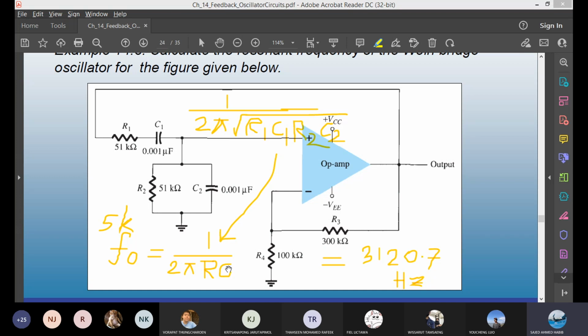If you remember the voltage control oscillator from linear digital circuits, VCO, for a good VCO there are some design limitations. The resistor has to be within a certain value, and then applied voltage, VC, and frequency all have to be within a certain value. Here you have a bit more liberty. We don't have such strict criteria, so you can pick any value of R which is sensible. For example, what you can find in the lab: 100K, 50K, 70K, etc.